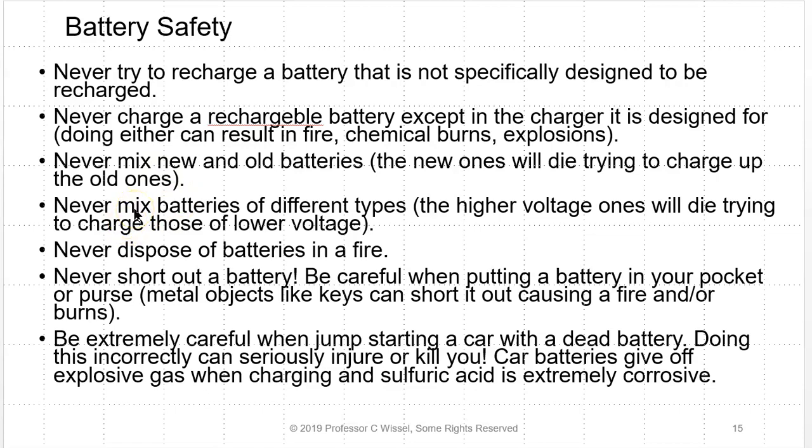Never mix batteries of different types. The higher voltage ones will die trying to charge those of lower voltage. Never dispose of batteries in a fire. Never short out a battery. Be careful when putting a battery in your pocket or purse. Metal objects like keys can short it out, causing a fire and or burns. And you don't want a fire in your pocket.